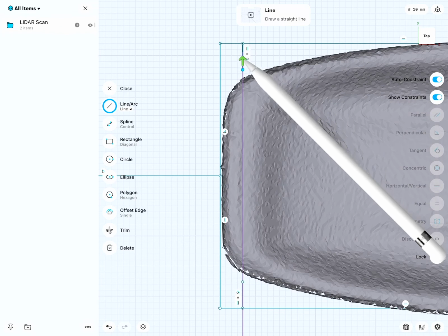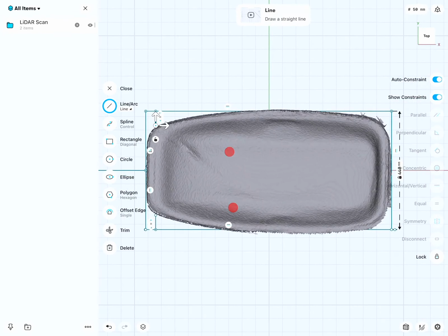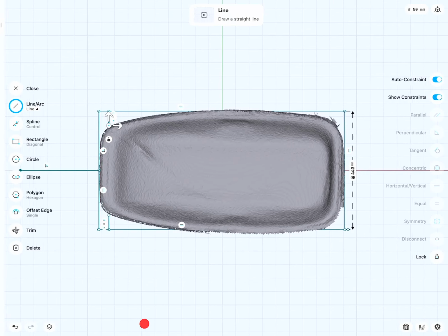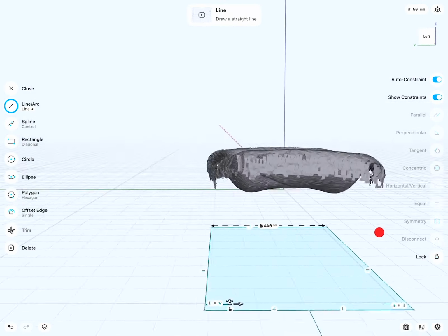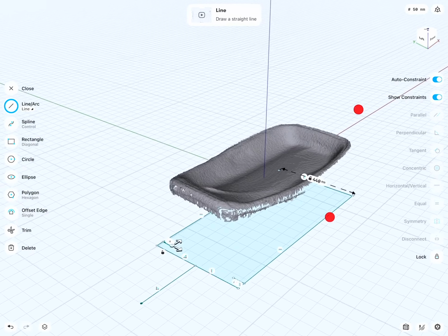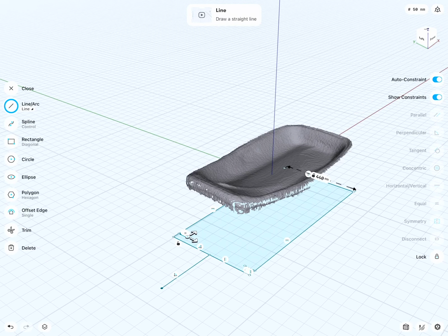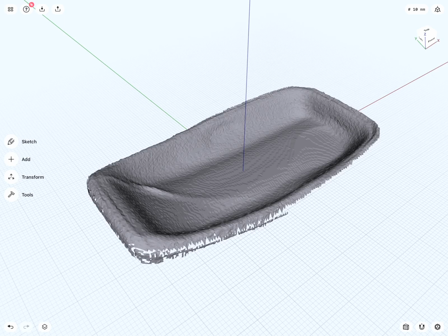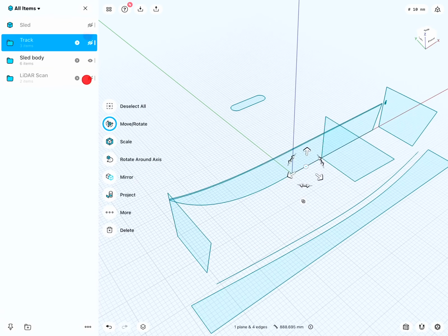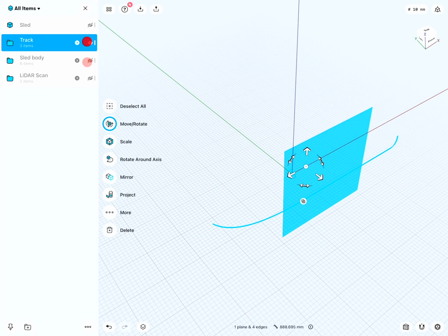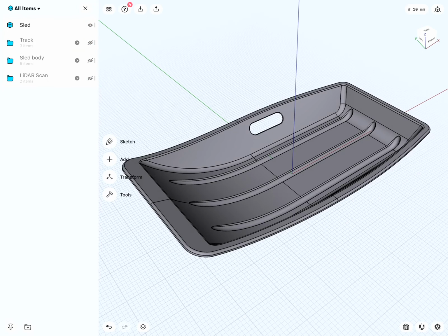And the more these elements line up, the more your scan is perfectly rotated. So we'll take a moment to position this correctly, but then this is a fabulous way to have a 3D scan, which we can then model over. So with the scan positioned, we can now take a look at how I created the individual sketches, so I could then create the final CAD model.